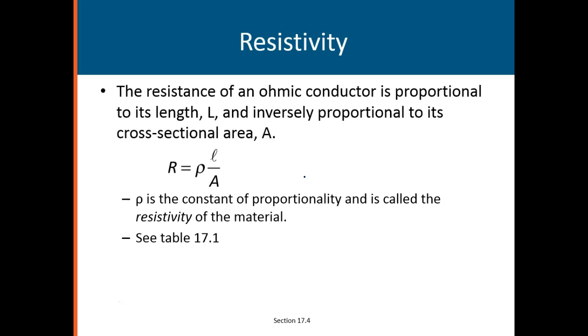The other thing that increases the resistance, have you ever really carefully looked at the filaments in the light bulb, especially some of those clear bulbs that you can see the filaments really clearly? If you'll notice, they're little springs looking things, coils like that. What does doing as a coil like that do? It increases their length. The greater the length, the greater the resistance, right? And the other thing, have you noticed how fine they are?